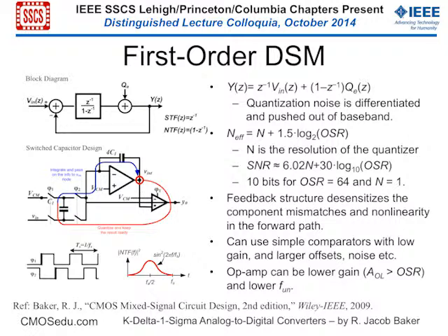And that's important, because when you use a 1-bit quantizer, you got a lot of quantization noise. Now, we don't use multi-bit quantizers, even though we get higher resolutions, because we get nonlinearities, okay? That's not to say for the application I'm going to show here that might still not be useful. The benefit then for simple oversampling is that for every doubling in the oversampling ratio, you get 1.5 bits or 9 dB increase in the signal to noise ratio. So this technique is very popular, or has been popular for audio.